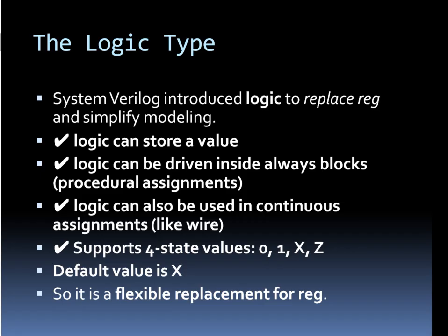The one thing in Verilog that always leaves new users confused is the difference between a reg and a wire. When driving code, which should we use? How about when we are connecting blocks? SystemVerilog improves the classic reg data type so that it can be driven by continuous assignments, gates, and modules in addition to being a variable. It is given the name logic as some people new to Verilog thought that reg declared a digital register and not a signal.